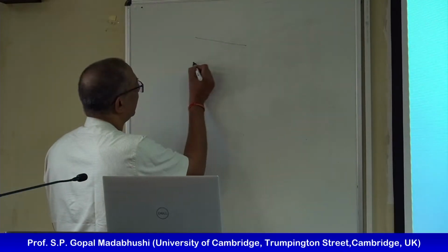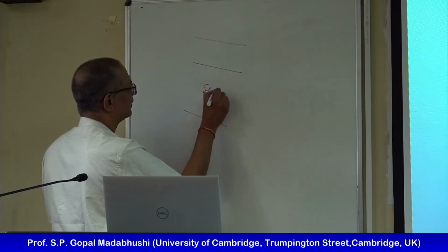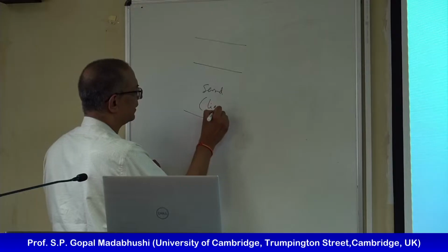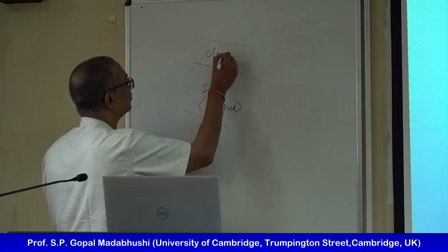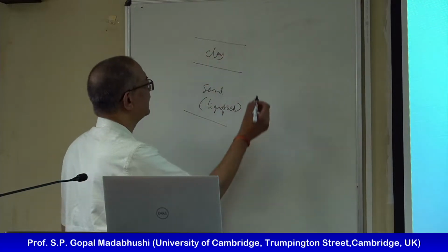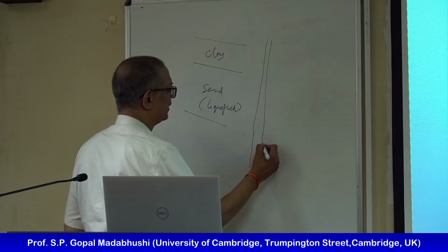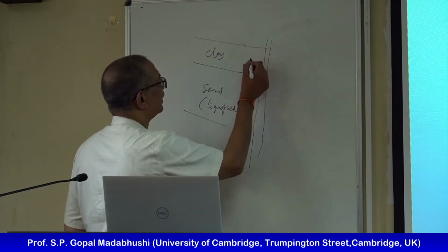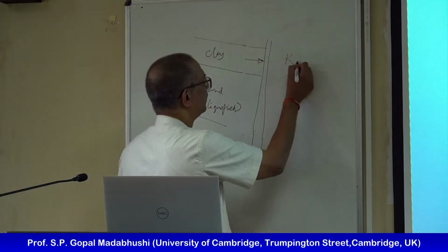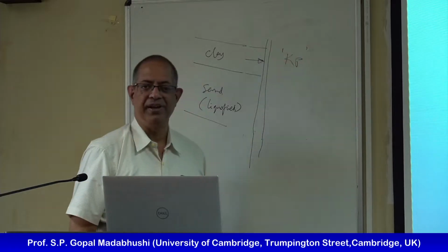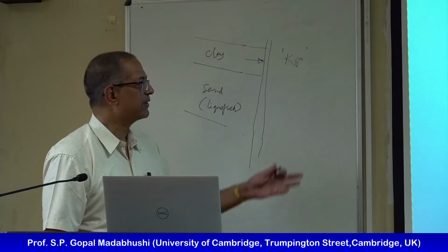So we got this is the sand, liquefied, and this is the clay. So what they're saying is, if I go to the pile, going like that, here apply Kp. Use Kp to work out the horizontal pressure. Fair enough, because that is clay.